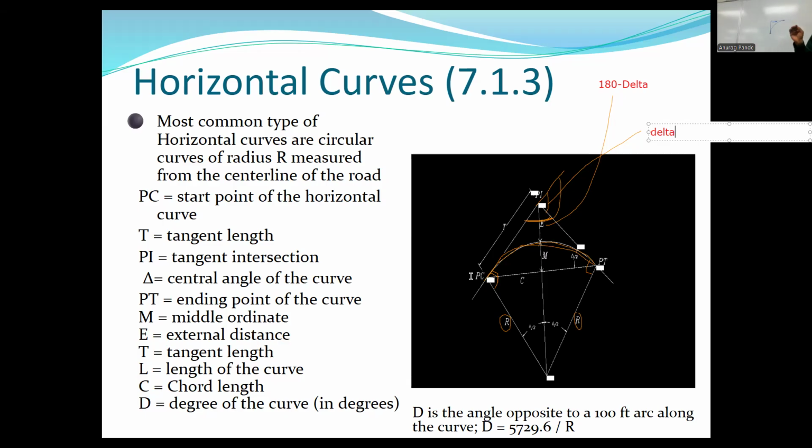Now, in horizontal curves, this is the most important thing. The length of the curve is measured along the curve now. Why? Because the curve is located on the horizontal plane. Does that make sense? Because we measure distances or length of the curves or length of the roadway alignment along the horizontal plane. And now my roadway along the horizontal plane is a circular curve, so I need to measure the length of the curve itself. So remember that.